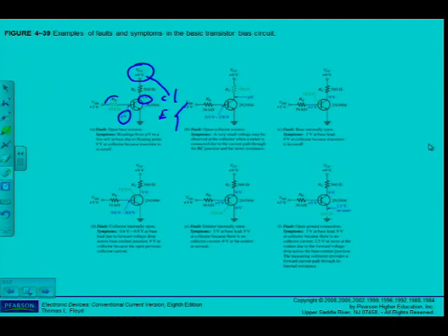It could be that the resistor RB is open, it could be that the track is broken before the base, or that the base terminal is broken or not making a connection. Actually, this measurement, as they show you, is just before the terminal of the base, so it should be the resistor or the track that is broken. Typically, that's where you would go look for the fault if you get readings like that.